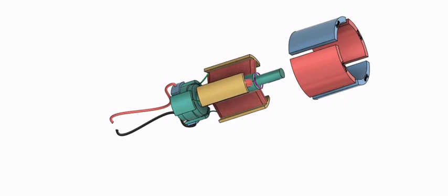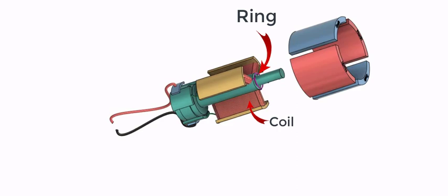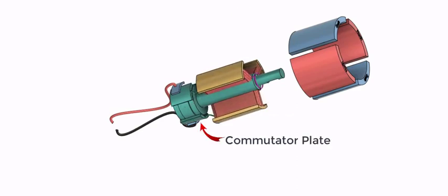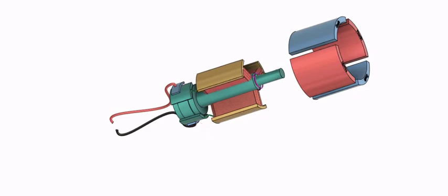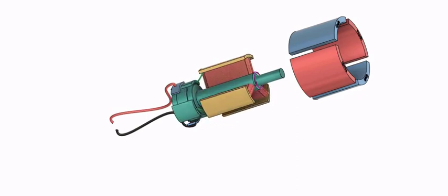The current then passes through the small ring on top to the other coil, which is connected to the negative terminal of the battery through the commutator plate and brush. This completes the circuit as the current travels from the brush, through the wire, and back to the battery. At present, the third coil is not connected, as the rotating commutator plates only make contact with two brushes at any given time. The commutator acts as a mechanical switch, providing or disconnecting the current source depending on its position. In this view, the two connected coils are receiving power.